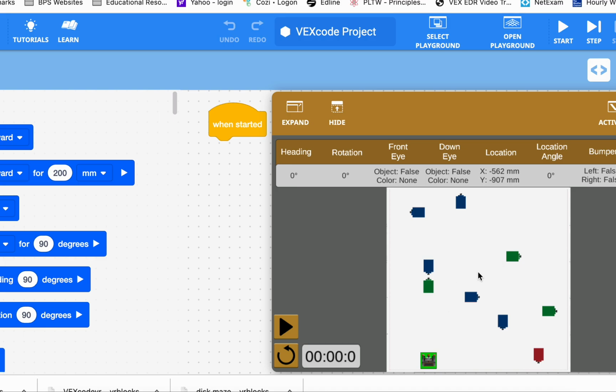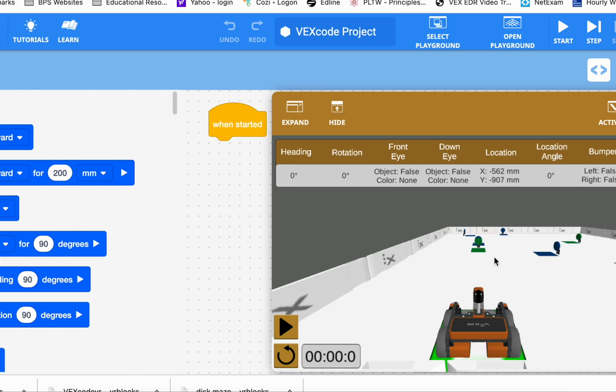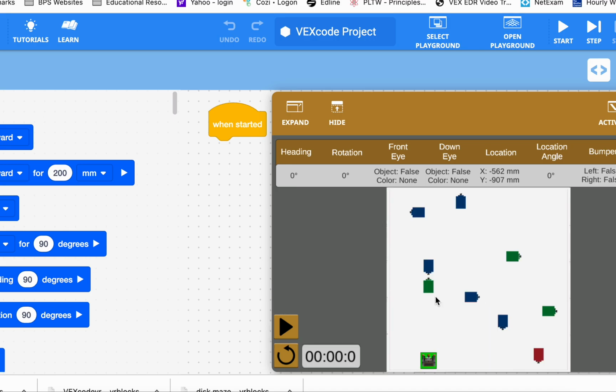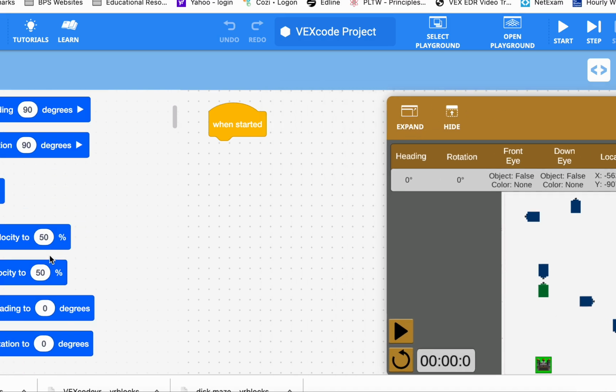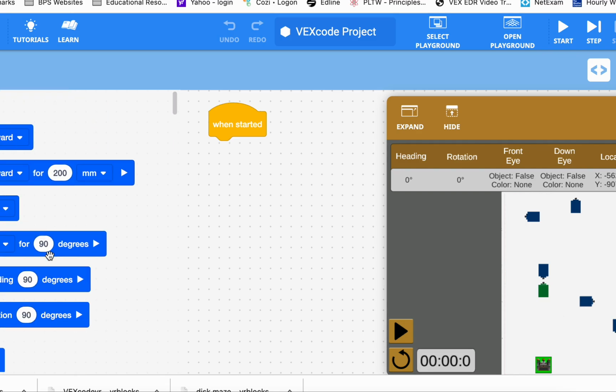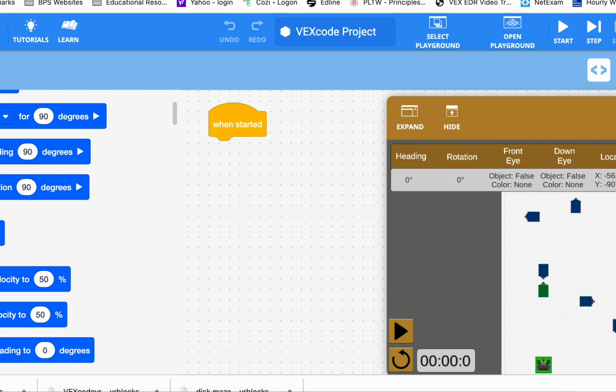It's asking the robot to visit all of these disks, which look like this from this view. You can see a base and a tree-looking structure. You can see they're different colors, and it's also asking the robot to finish on the red disk. All right, so let's use a while loop to keep us moving. I'm going to set the velocity right away to something faster.